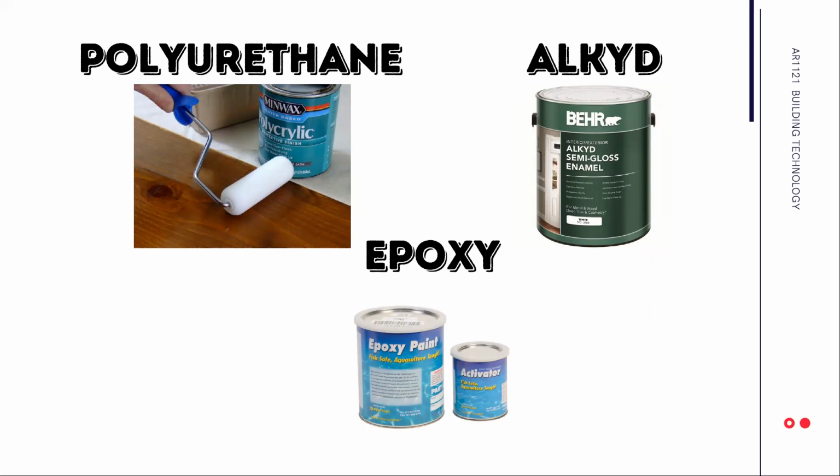Polyurethane paints, sometimes called simply urethane paints, cure by chemical reaction or by exposure to air, heat, or UV light, and are available as one and two-part coatings. These are particularly useful as color coats where a tough, highly aesthetic finish is desired, as for automobiles. Epoxy coatings are usually two or three-part formulations and impart good abrasion and weathering characteristics and high resistance. Alkyd enamel coatings provide environmental protection in interior, exterior, underwater, and underground applications, and are also used for road markings but tend to be slower drying than other paints.